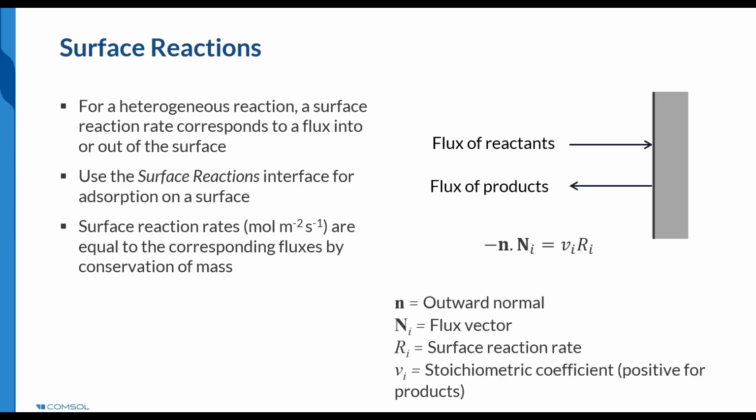At the surface, concentration gradients will develop to match the flux and the demand of the species at the surface. In mass transfer limited systems, we might also observe quite significant concentration gradients, and this is where we can investigate whether mass transport limitation will reduce our observed reaction rate. This can be quite useful when simulating the system, as it's quite difficult to determine this experimentally.